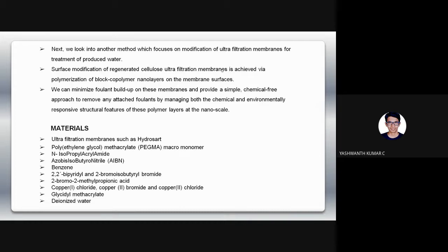To increase the antifouling properties of this modified membrane, PPEGMA is grafted as a second block. The dramatic reduction of flux to unacceptable levels as a result of alteration of the membrane was one of the key issues discovered. By switching to a more open ultrafiltration based membrane, the following method can be employed to solve that problem. The surface of these ultrafiltration membranes has been modified to provide responsive chemistry while maintaining high flux. Water quality versus permeate flux can be optimized by using a more open membrane.